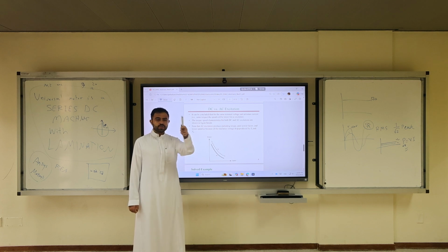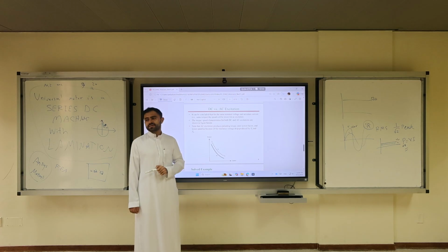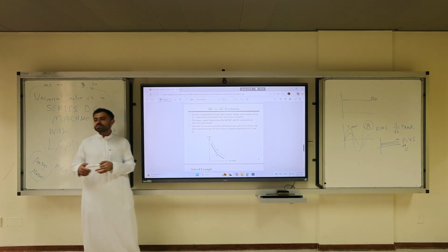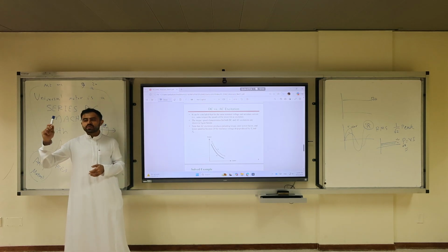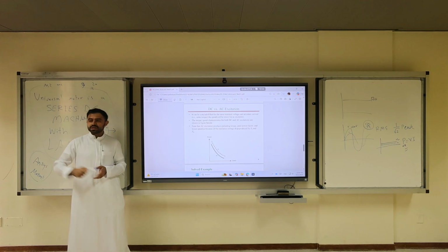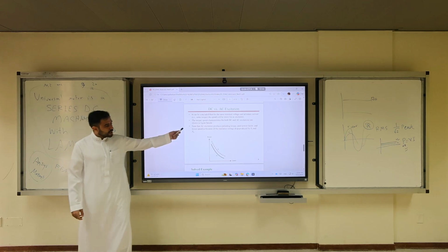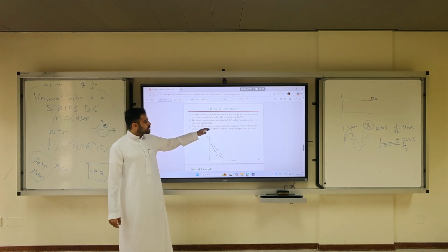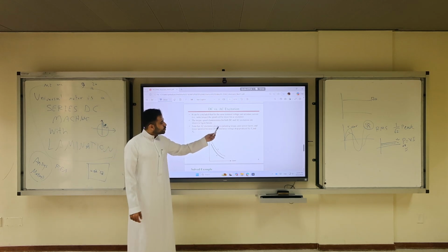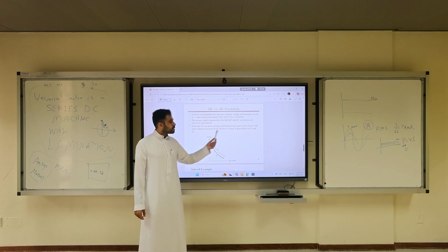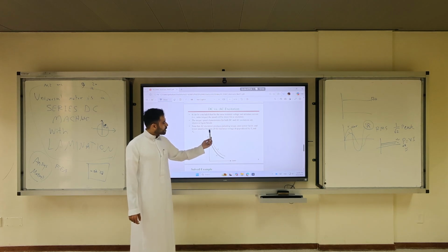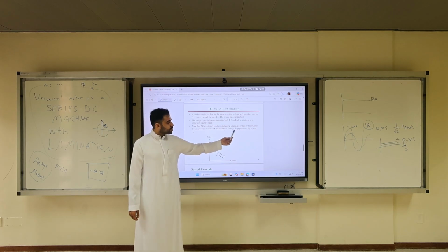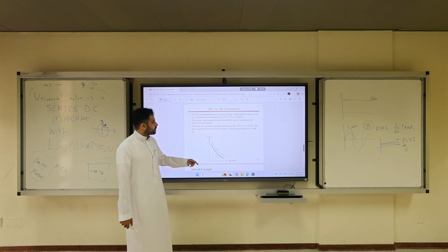Rather than one phase, you apply three phase. Do you remember in the 360 course they told you three phase is good for machines? Yes, because it's smooth. So that's what we mean here. AC excitation, which is single phase, produces pulsating torque, poor power factor, and lower speed because of the reactance voltage drop produced by XF.